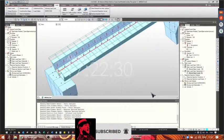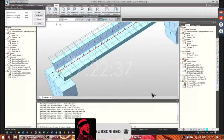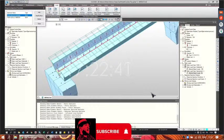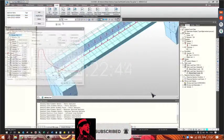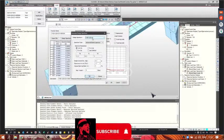Now, it's time to define the dynamic loads. We go in RS function. We define two response spectra, one for horizontal direction, one for the vertical one. Here we choose the design spectrum. We have P100 as an option here. Horizontal design spectrum. Here, in the zone of Sinaia, we have TC equal to 0.7 and a ground acceleration